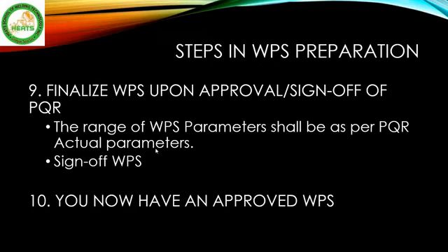Upon transferring to the PQR, you can create and finalize your WPS upon approval and sign-off of the PQR, because once the PQR is signed off and approved, you can finalize your WPS and send for approval. Or there is also a possibility that you finalize both the WPS and the PQR at one time and send for approval and sign-off at one time also.